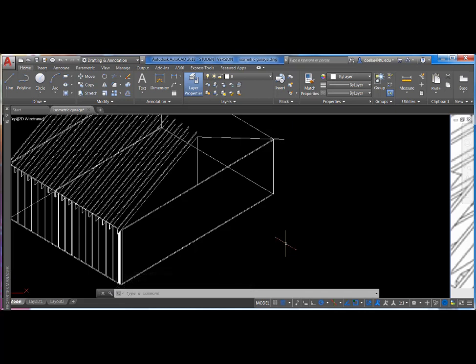So you can see now we may want to do some things here to help ourselves, and so now I've created a couple of layers. I'm going to take some of my items and move them onto different layers to make it easier to work with. So right now you can see I've got some pre-created layers, rafters, studs, and ellipse, in anticipation that we're going to do the ellipse cutting out the roof hole.